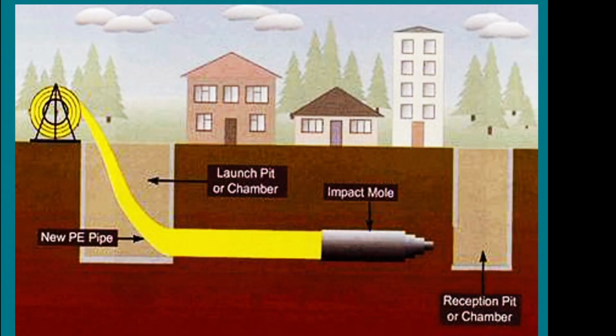The main part of a rig for impact moling is a hydraulic cylinder with a capacity of 36 tons. A two-cylinder 4-cycle gasoline engine starts the hydraulic station. The location system consists of a probe placed in a removable drilling head and a locator, defining the location, depth of the drilling head, angle of vertical inclination, and charge level of the probe battery.